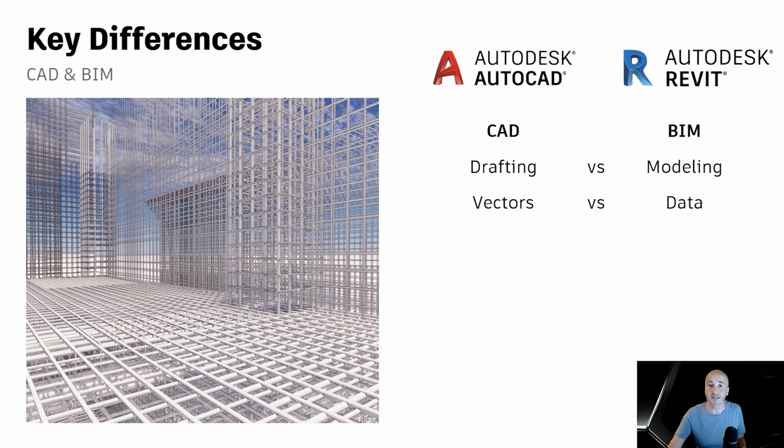Each of these elements has its own settings and parameters that establish the kind of object it is meant to represent, and the entire group of structural elements comprises a single model. This model may be viewed in plan, section, elevation, 3D or schedule views as desired, and users may define rules for each of these view orientations to ensure they match individual firm standards.